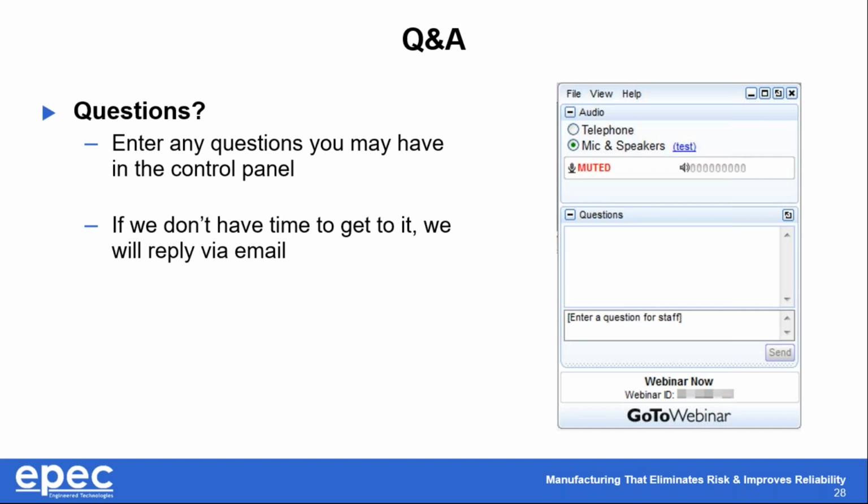All right. The next question here is, what about solid conductor wire? Does this impact UL? Well, this is a good question. So there's usually no impact to UL because most wire types are actually dual certified for both a single solid strand of wire as well as the multi-conductor strands of wire, something that's highly flexible, almost looks like a wire brush type of cross section.